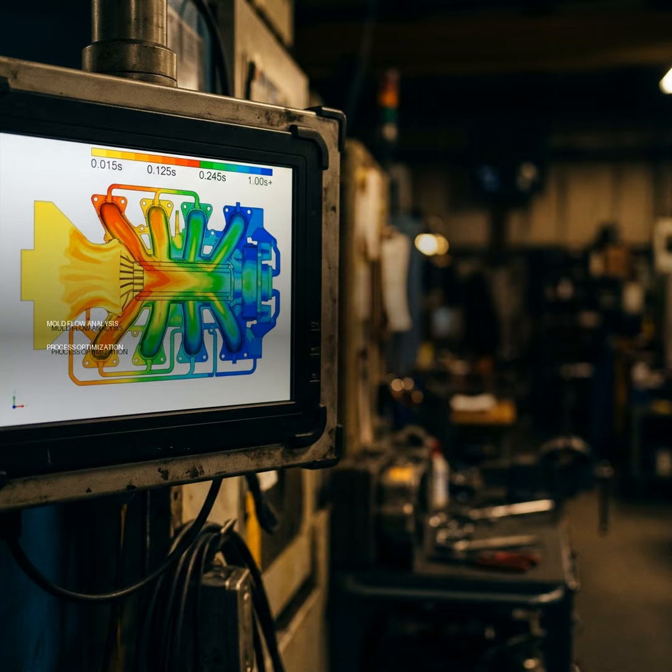That's where the rubber meets the road. A good report starts with basic information: project number, resin, part number, cavity count, date, the software version, the analyzer. It'll also list key parameters like melt temperature, mold temperature, and the maximum injection pressure.